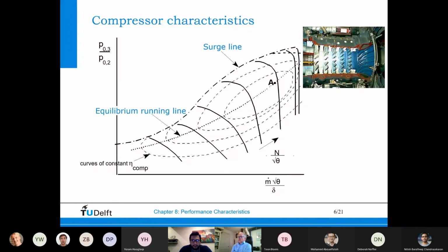So near point A, regardless of what you do, of inlet temperature, etc., you always stay on that dashed line that is going from bottom left to top right. At the lower region, it may change a little bit, but at steady state, you stay on the same line, unless the condition of the compressor changes or other component characteristics change somehow. So, for example, due to deterioration or corrosion in either the compressor, or can also be the downstream turbine.